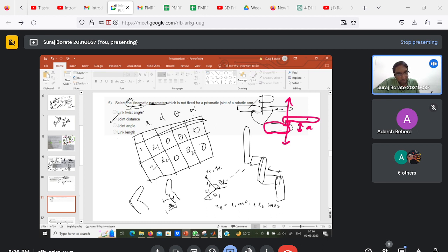But in case of DH, we are measuring the angle with respect to the current axis. So this is theta 1 geometrically, and this will be theta 1 plus theta 2, and similarly ye will be L1 sine theta 1 plus L2 sine of theta 1 plus theta 2. You can verify this later. Okay, this is just by geometry, and it is very simple. It's just two lines of code, but we want to see how to do it by DH parameters.